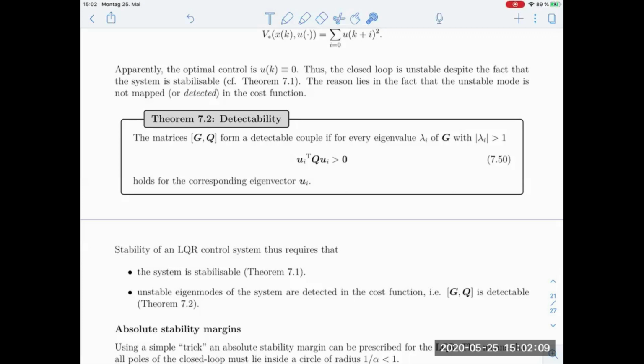But it's important. Look into the optimal controller material that we went through today. I know it's a complex matter, but it's highly useful in practice, and it's really important that you understand the basics and the application of an optimal controller, and that you make yourself comfortable and proficient with using, designing, and playing around with, for example, an LQR in MATLAB. That's essential, also for the exam, but it's also essential for applying efficient, model-based control in practice. That's really one of the practically most useful controllers that you can apply, that can yield a very fast and also quite robust control performance for even multivariable plants.